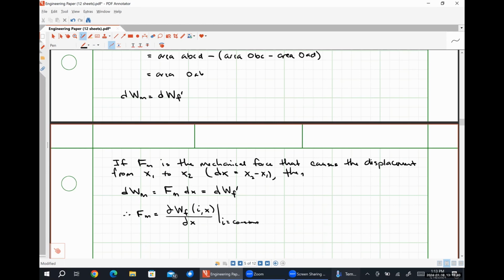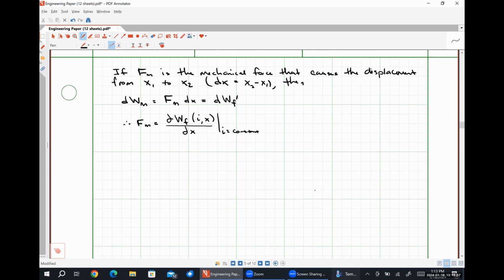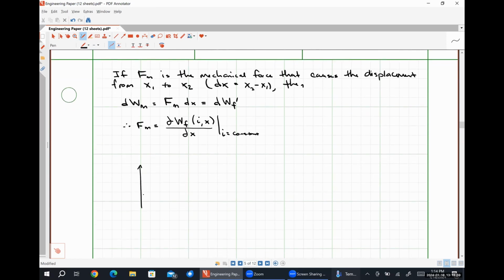Now, let's go the other way around, and let's say that our plate moves very, very fast. For a fast movement, the flux linkage is effectively going to remain constant during the motion. So if I plot things out here again, where this is lambda, this is I, I once again have two curves, x equal to x1 and x equal to x2.